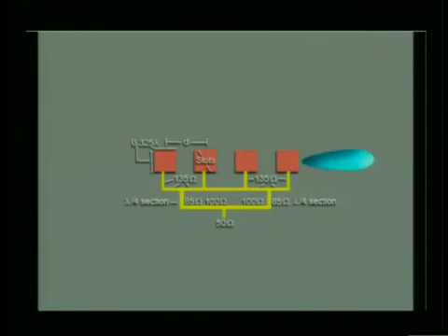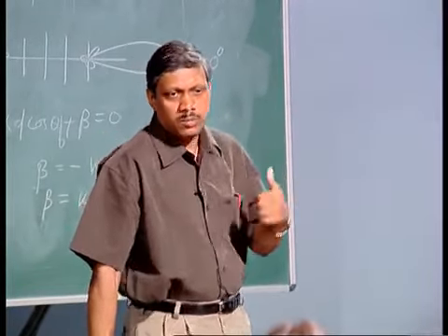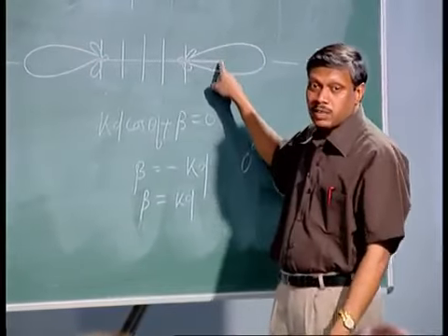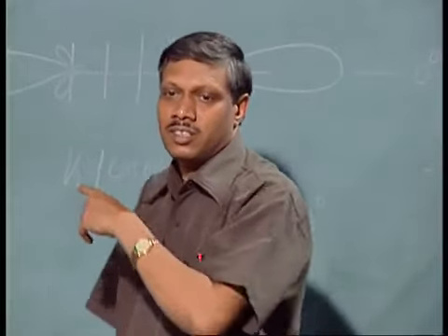So, how the endfire array will radiate, you can just have a look. You have radiation in the 0 degree direction with certain minor lobes along with the main lobe. Similarly, you have radiation which may be in the 180 degree direction. As I have already told you, in this situation, in the 0 degree or 180 degree, you may get maximum field, but this ordinary endfire array does not guarantee that maximum directivity will be in that direction.